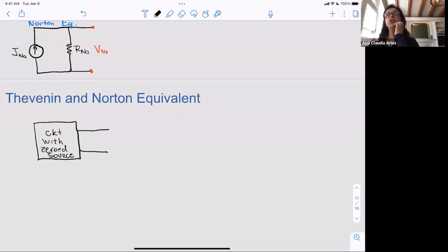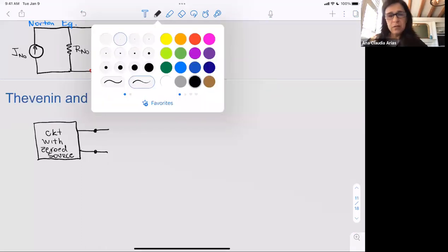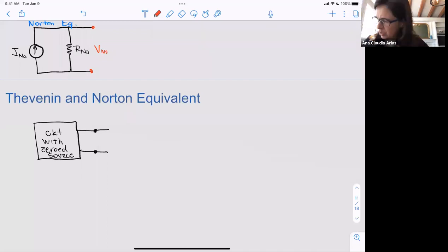Just like I showed you how to measure voltage and how to measure current, we can do the same here, where I'm going to connect this to the outside world, and I want to test things. So to test, I could hook up a voltage source here, which I'll call V test. And by hooking up this voltage source here, I know I'm going to have an I test.